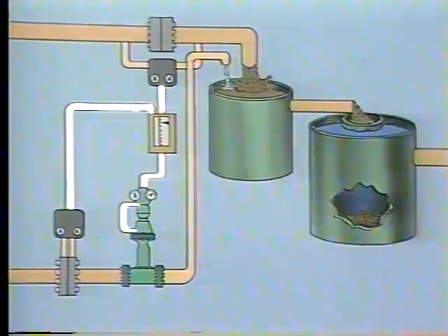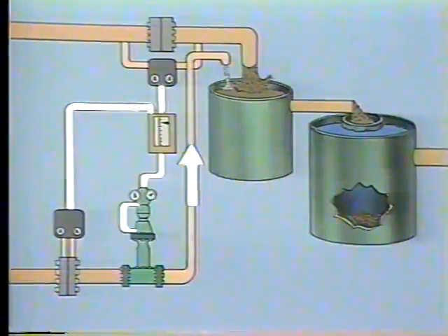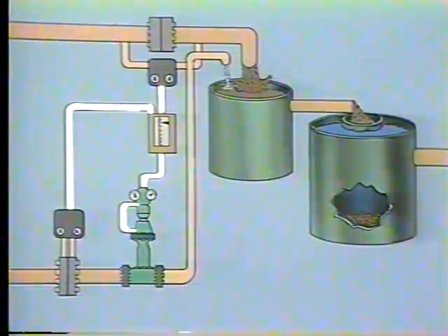If there is still a difference between the signal that represents chemical flow rate and set point, the controller continues to send a corrective signal to the final control element. The final control element manipulates the chemical solution flow rate until the signal from the chemical flow transmitter and set point are balanced. When this occurs, the system is in balance and the proper ratio of chemical solution to wastewater is achieved.